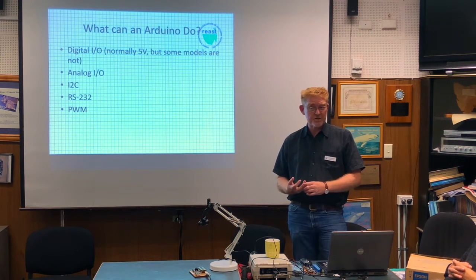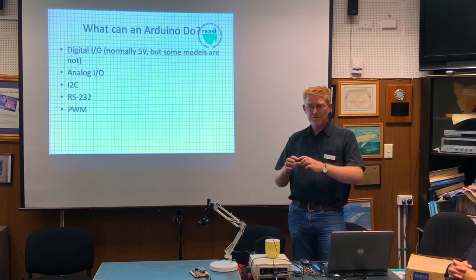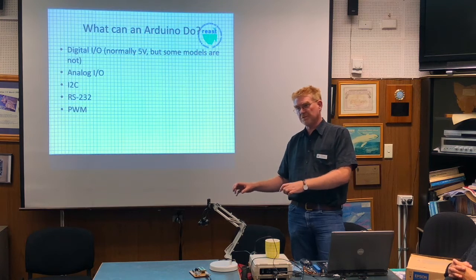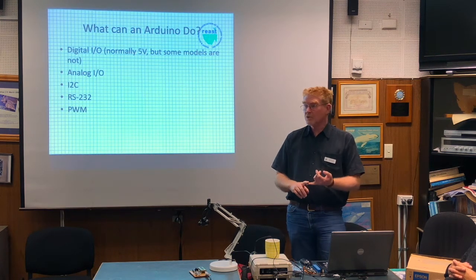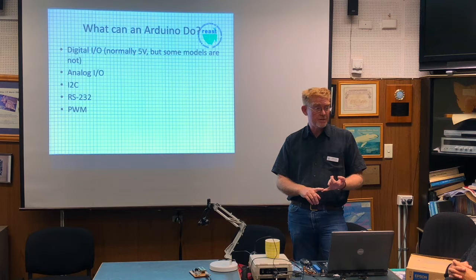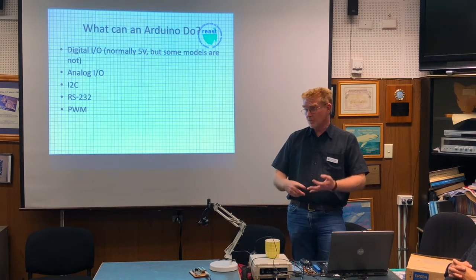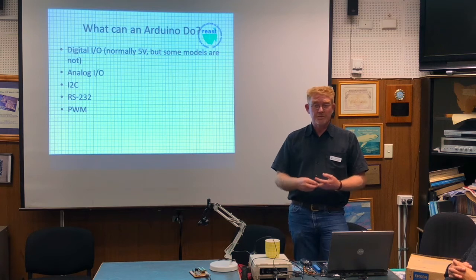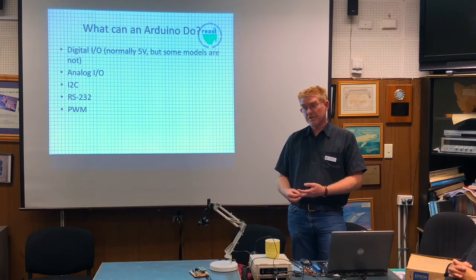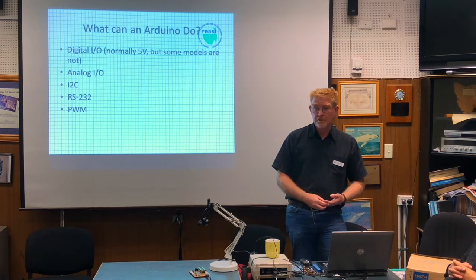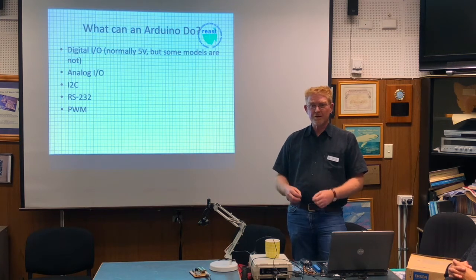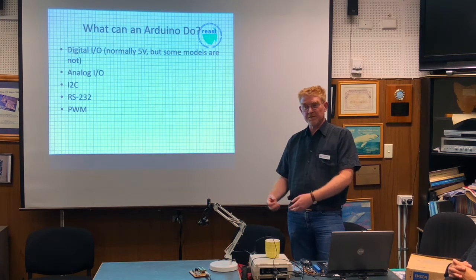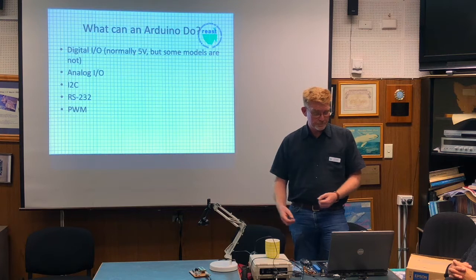I2C is one of those really cool protocols that takes 2 pins from your microprocessor and lets you put on a bus a whole range of different kinds of chips. You can get real-time clocks that talk over I2C. You can get I/O expanders to give you more digital I/O. I've seen chips that will talk to an LCD display over I2C. You can get rotary encoders, all kinds of gadgets where you can share those 2 pins on a microprocessor and do really interesting things with them.